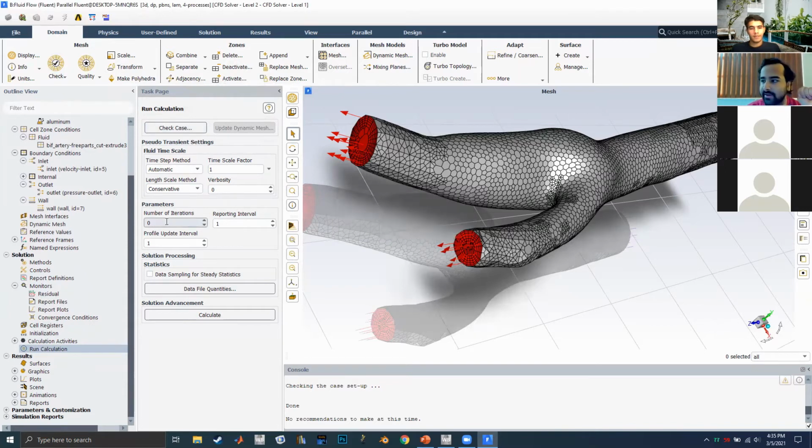And we select how many iterations we want. By default, I'll usually just pick a really big value, because as long as your solution is continuing, it's going to eventually reach convergence. For us, it would be those 1e-6 values. Once it reaches those values, the solution is going to end and we're going to get our results. But if we select too few iterations, it might never get to 1e-6. So I just pick a really big value, like 2000, and we're probably going to reach convergence way before this anyways.